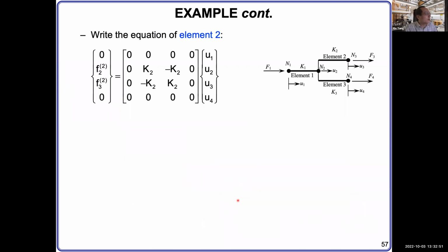And then we have element 2. If you just put element 2 in, then element 2, which is this one, is node number 2, node number 3. So it's in position 2, position 3, row 2, row 3, column 2, column 3. So you have this K added in, and then don't change the displacement here. Only put the force number in the force column.